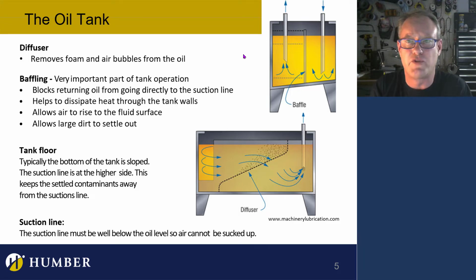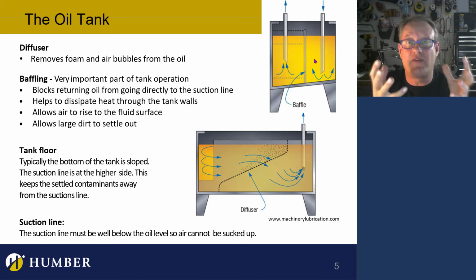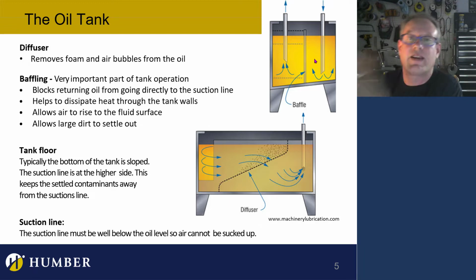There are drain lines in other valves, and that's a separate line that goes back to the tank. That drain line doesn't have to be under the liquid, although it often is. It's not as important as for the return line. The drain line is often just little trickles of fluid that end up in the valve and have to vent out somehow.